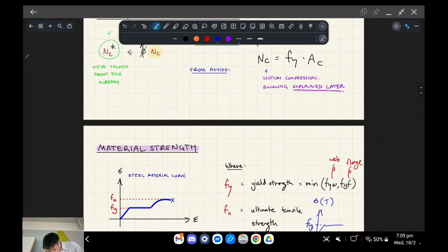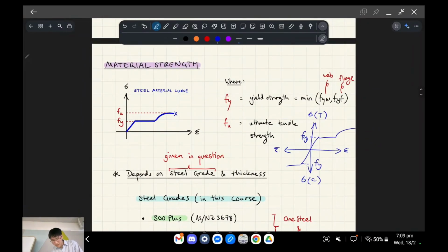Okay, but for tension design, we actually consider a little bit of what happens past the yield strength, which is strain hardening. If you remember that from material science. It's where you have these micro fractures in the material, and they start to develop resistance. So there's a little bit of extra juice at the end. It gets stronger just before it's going to fail in a brittle fracture. So that yield strength, we call that ductile failure mode.